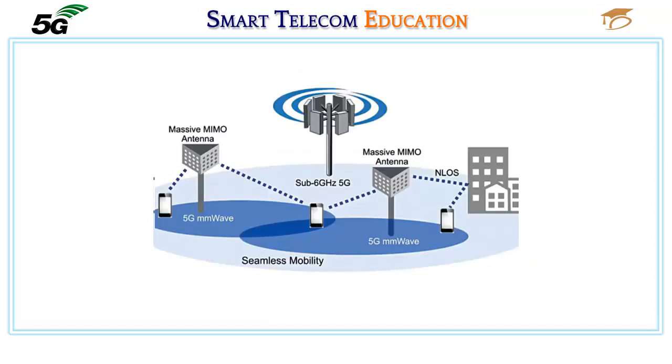Although 5G relies on existing network infrastructure and concepts, there are several new features to 5G. Such features are the new radio, NR, and new core, 5G-C, and operation in high-spectrum bands, millimeter wave, with massive MIMO antenna systems.